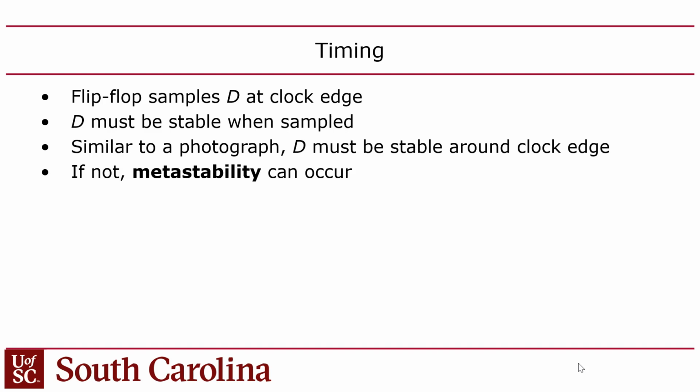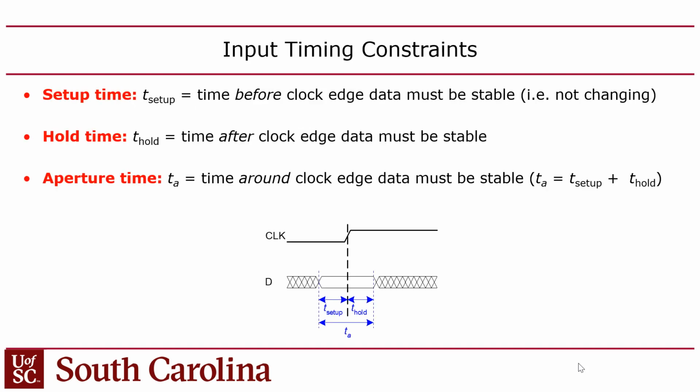So the logic in a CPU is going to be comprised of logic paths that begin with a memory element and end with a memory element. The memory elements are often registers. Okay? So registers have this notion of a setup and a hold time.